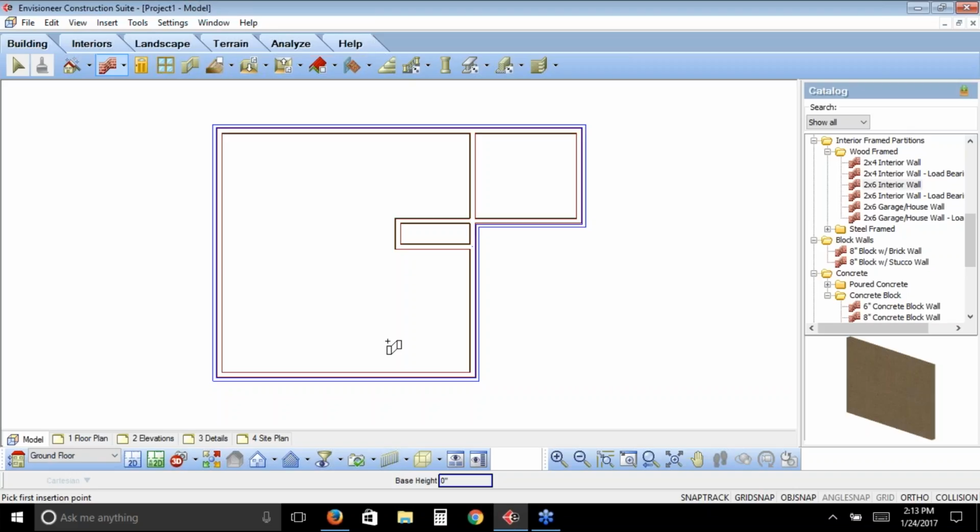The next tool that I want to show you when you're drawing walls is what if I know the distance that I want to start a wall away from a corner. As an example, I'm going to move my cursor just up on this existing wall that's here. Notice when my cursor is on top of that wall, I haven't left clicked, I'm just simply placing it over top of that wall, the dimensions automatically appear. It's guiding me to show how far away I am from each of those respective corners. So I'm 3'7.5" from the upper corner, and I'm 4'7.5" from that lower corner.